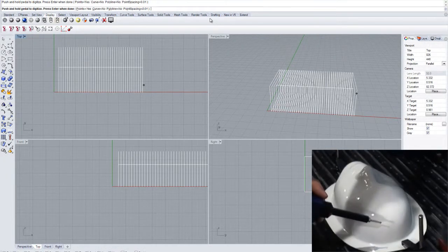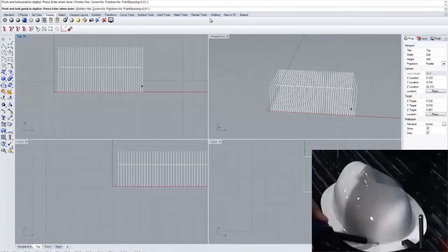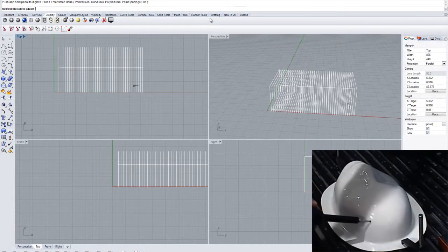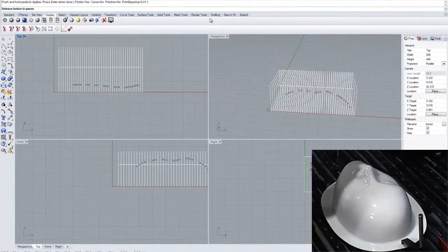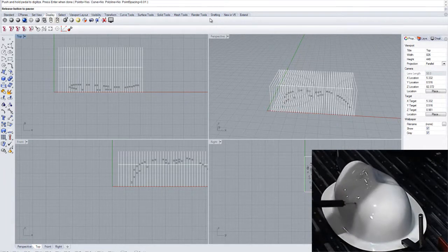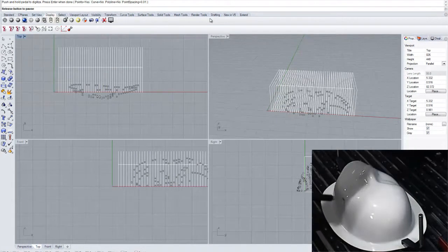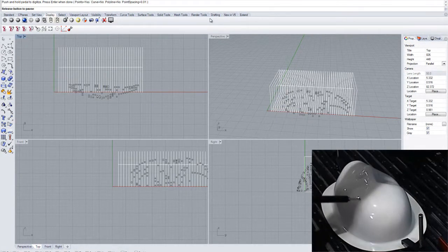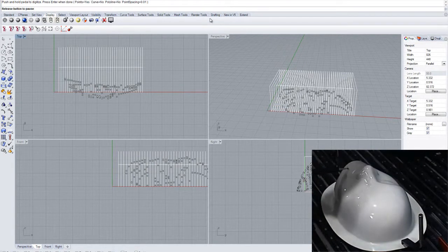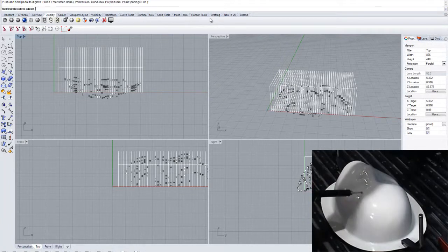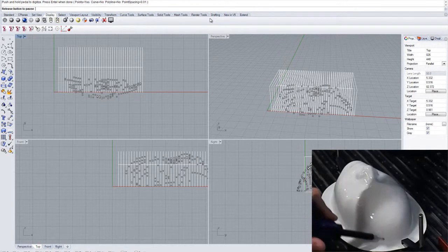All right, I'm going to hold the trigger down while the probe's engaged to the part, and I'm just going to start dragging the probe across the part. As you'll notice, you'll start to see those points show up. As the probe trips through each plane, it uses the plane to trigger the device to grab the points. So we'll just keep scrubbing. This is a very economical way to create a point cloud, much like what our white light scanners and laser scanners do for point cloud creation. We're going to use some of that functionality to create the surface in just a minute.